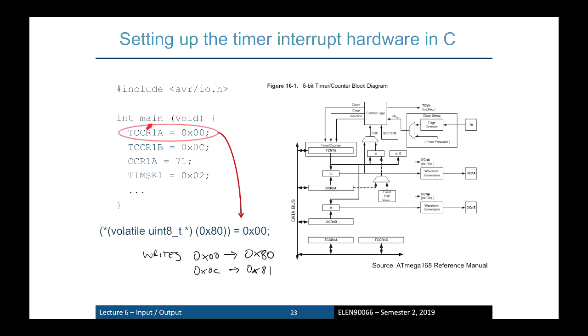Okay, someone pre-packages them in a header file for you with English names so you know what they are. So that's what that's doing. You are dereferencing, you can just point to it, dereferencing memory location 0x80, and you're writing into it 0. So you're actually writing into a register. It's a memory-mapped register.